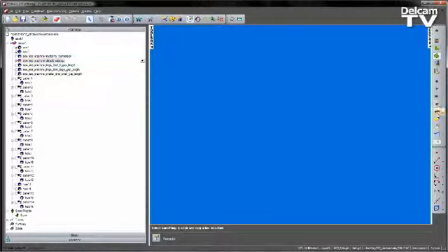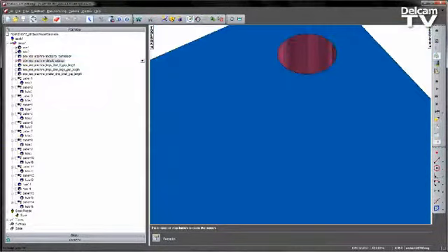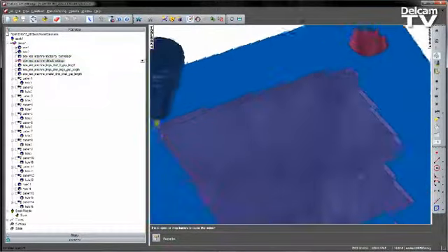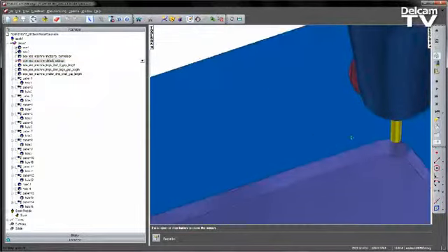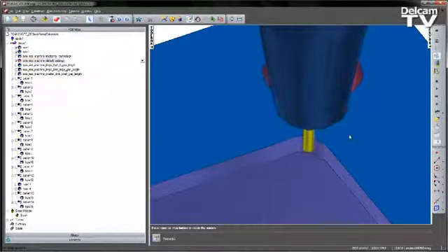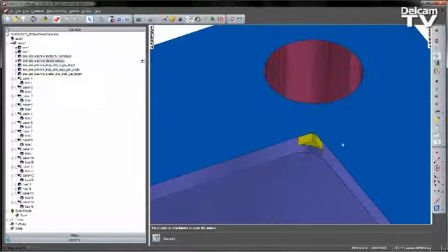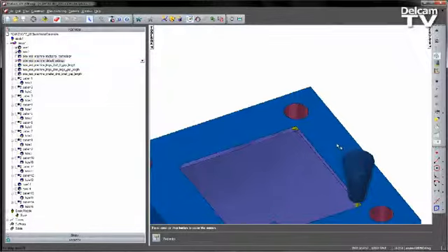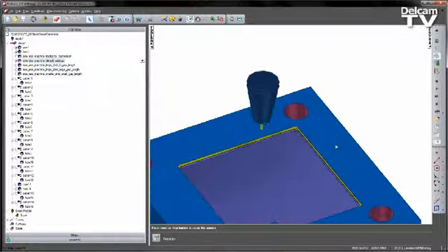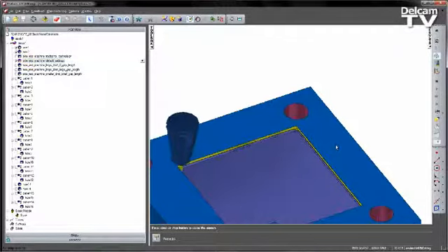If we look at this again in our 3D simulation, just rotating the view around, machining into this region, you can see we get the pocket being machined in each of the corners. Then we can see the pass going around the outside, taking that depth. So to make this more efficient, we're going to utilize some of these new stop model options.